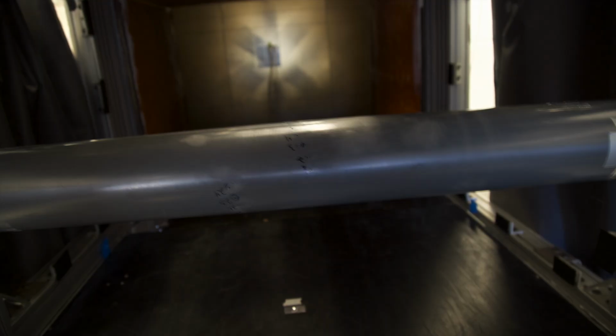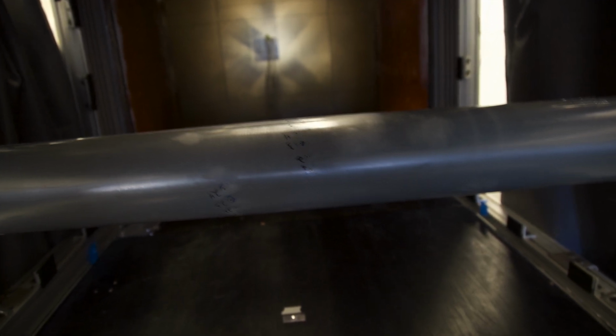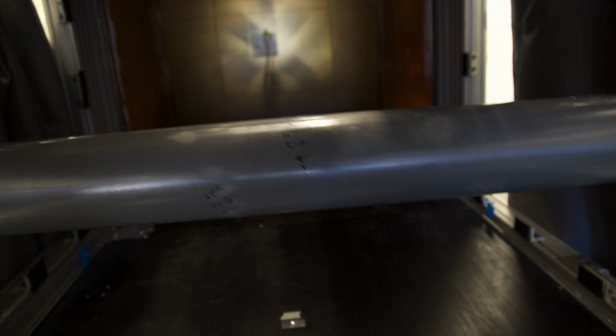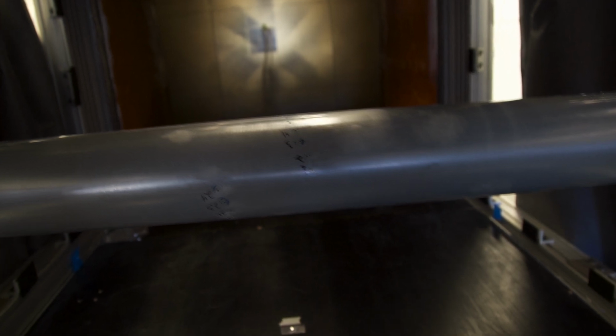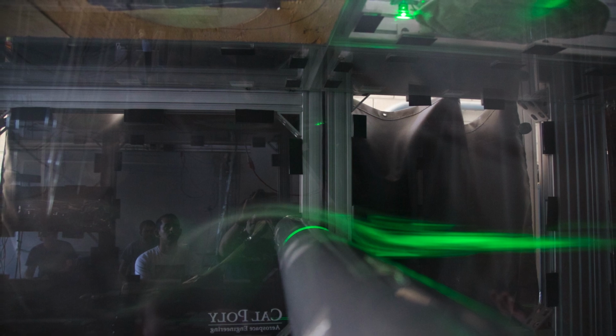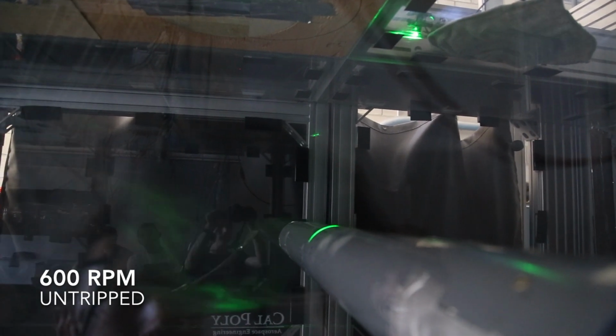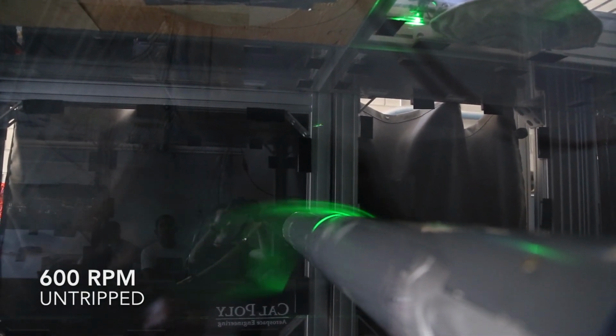Note how the ports were placed in a spiral around the cylinder and offset from each other. This is so any turbulence caused by the change in surface geometry does not interfere with the readings of any other ports. At each speed, a team member on top of the wind tunnel shined a laser down. When a smoke trail was introduced into the stream, it reflected the laser and revealed the characteristics of the flow. With some communication and adjustments, the different behavior of the air around the cylinder could be seen at various speeds.